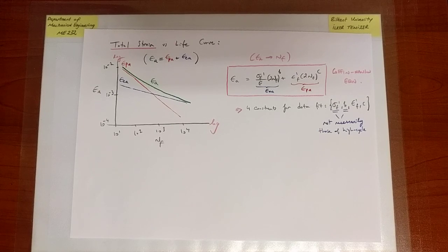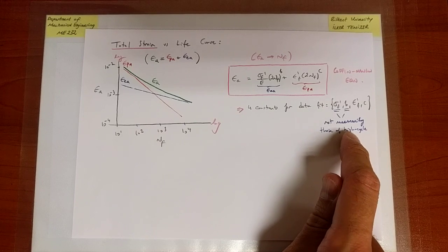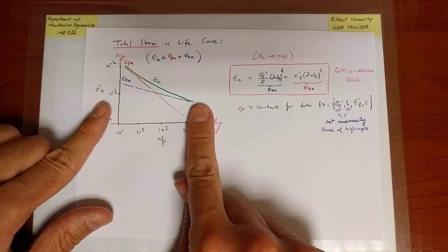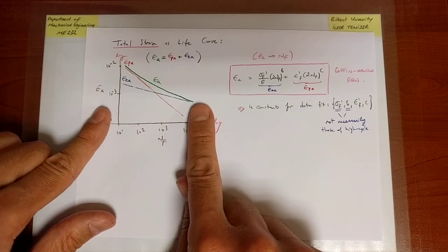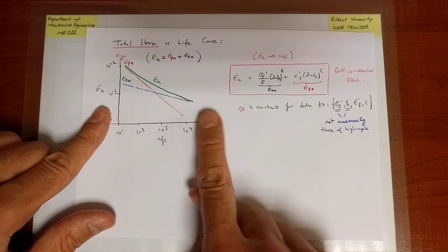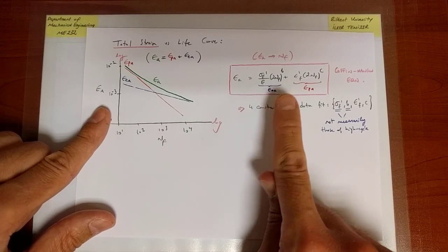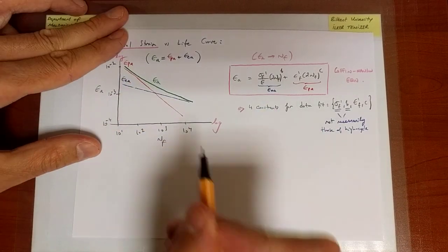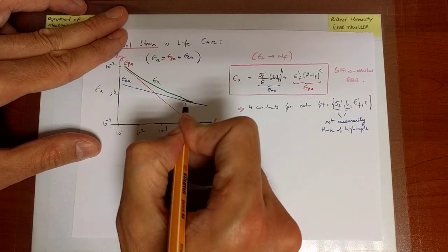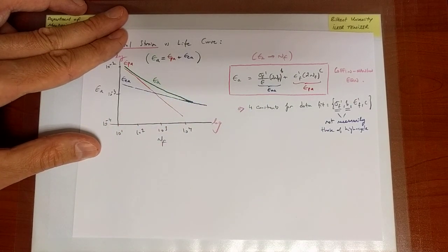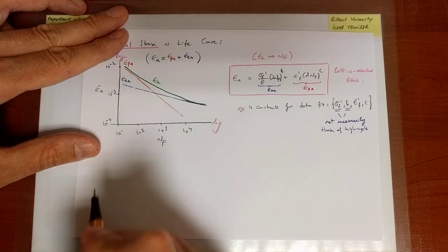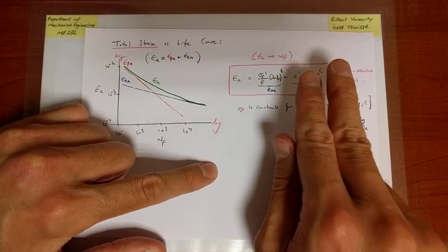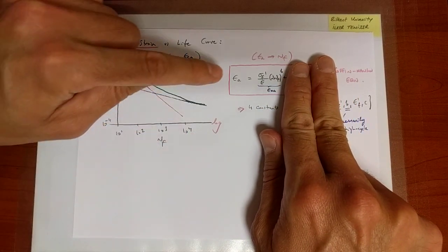If we were able to determine these constants not over a small range of cycles that is predominantly in the low cycle regime, but collect data over a broader range that moves into the high cycle regime, then as I proceed further into higher cycles, we see that the total strain is almost only elastic. In other words, the plastic portion is going to 0, so this portion is omitted, and we end up with a relation.